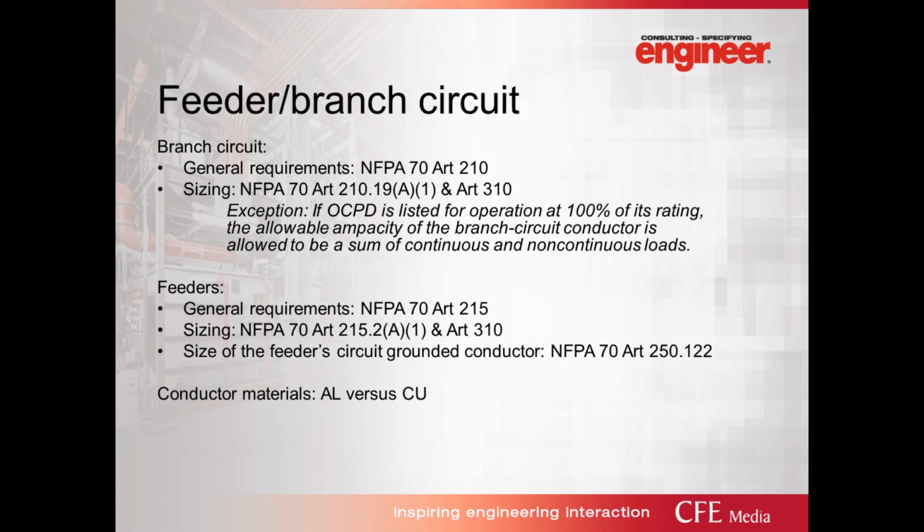In most of my projects, we provide copper throughout the building. I do see aluminum sometimes from the medium voltage utility transformer to the building switchboard or switchgear. Some critical applications, such as hospitals, may not even allow aluminum on the project.